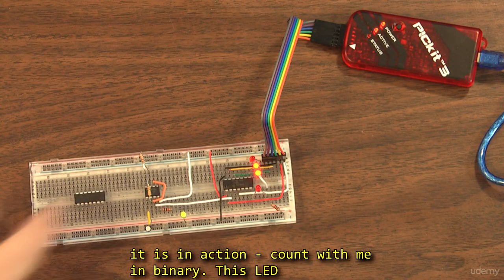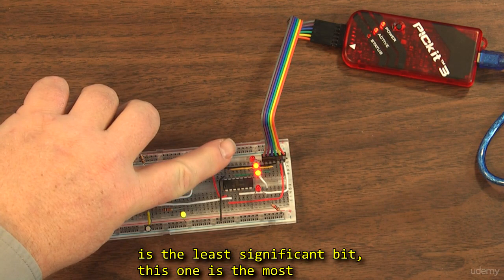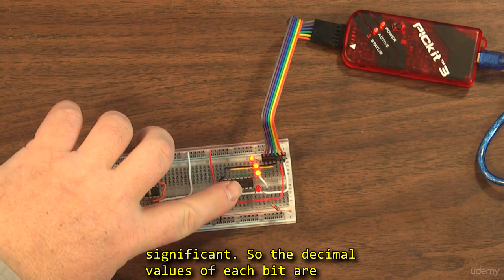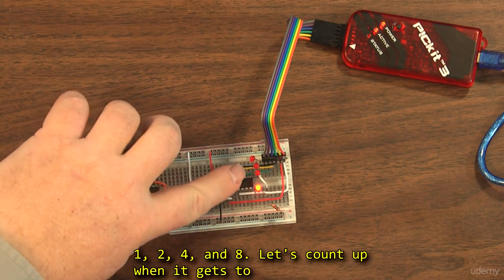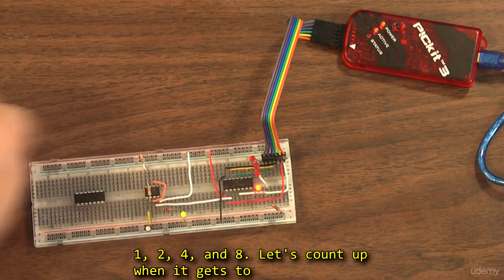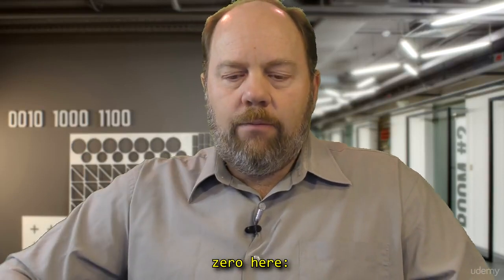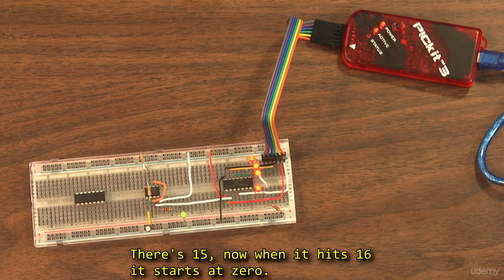Count with me in binary. This LED is the least significant bit. This one is the most significant bit. So the decimal values of each bit are 1, 2, 4, and 8. So now let's count up. So there's 15. Now when it hits 16, it starts at 0.